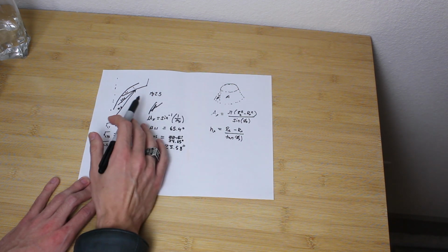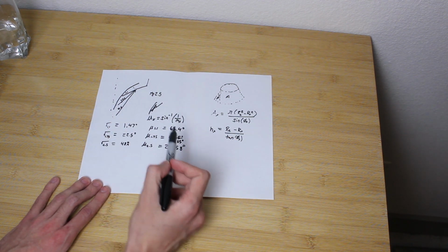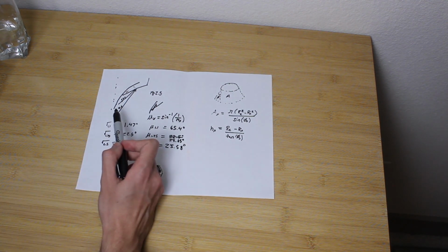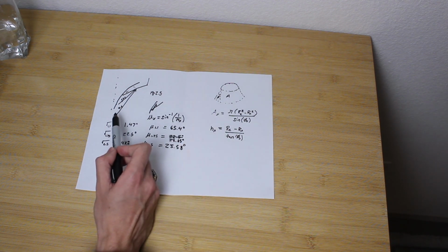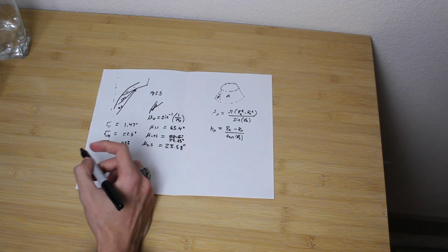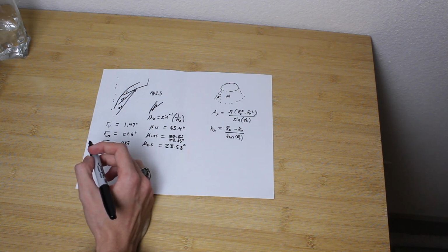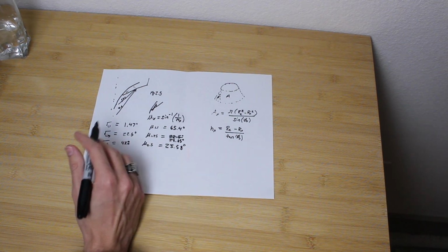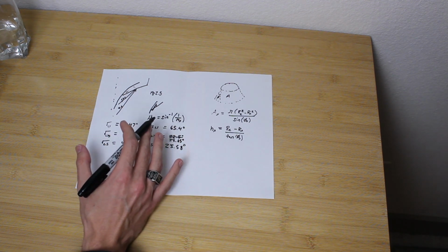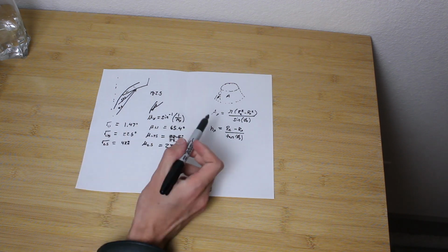Because conservation of mass says that all the mass going through the throat needs to be leaving the nozzle, and since we've decided that the nozzle ends at Mach 2.5, the frustum defined by Mach 2.5 must contain all of that conserved mass flow. The derivation of this equation is incredibly messy, so I'm just going to write it out here and just know that it's derived from essentially saying that m dot t equals m dot e, that is, mass flow at the throat